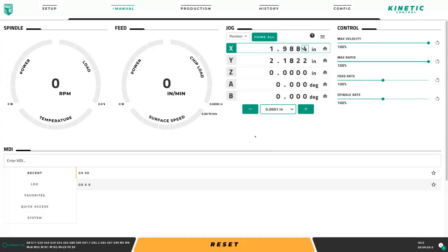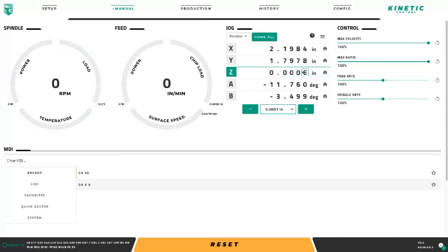So right now I'm just pushing keyboard buttons to jog individual axes, but we definitely wanted the UI to be mobile friendly for touch devices, so you can just click and drag any one of these digits to move a very specific amount, or you can jog continuously by just clicking these buttons down here. And all of these interactions can be bound to key bindings, which makes it really easy for someone in the field to create their own pendant. They could just hook up a keyboard and bind specific key bindings. Actually, if you check out our forum, someone posted today about their little Raspberry Pi project that has a custom keyboard with all the bindings to manually control the machine. So we wanted that to be really flexible.